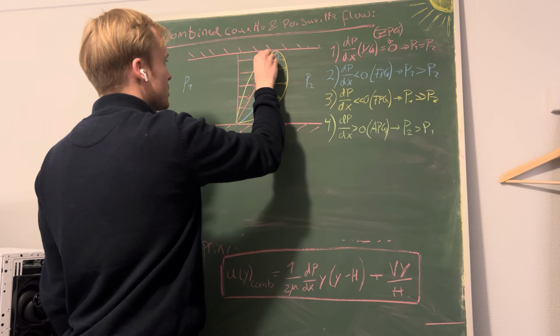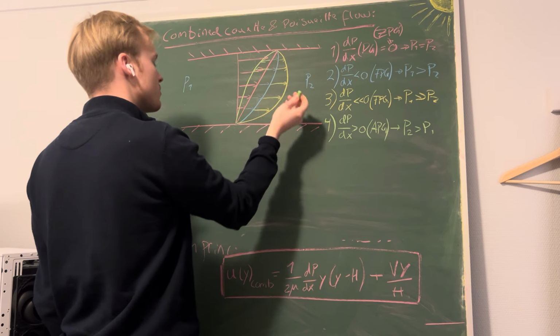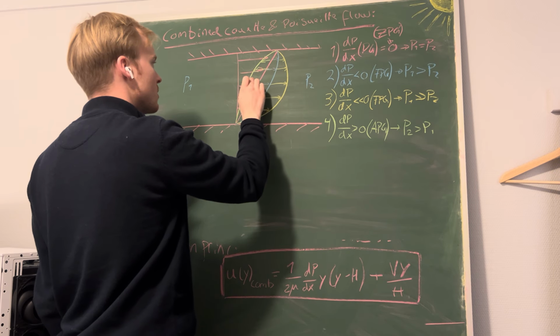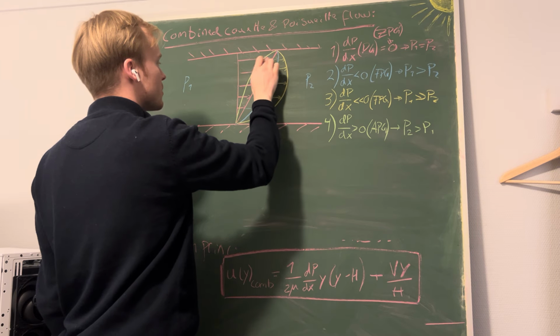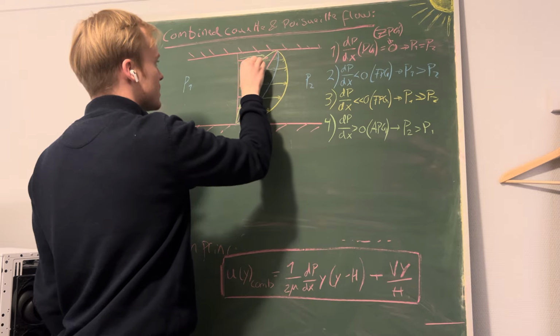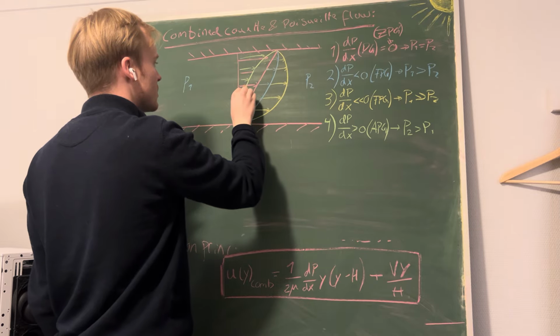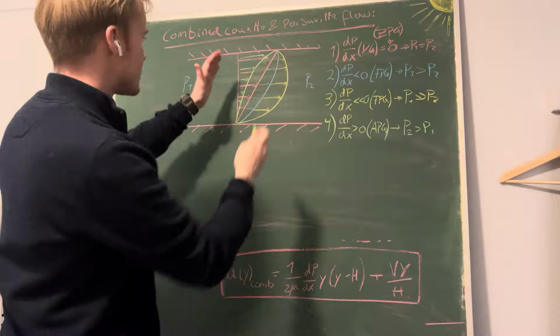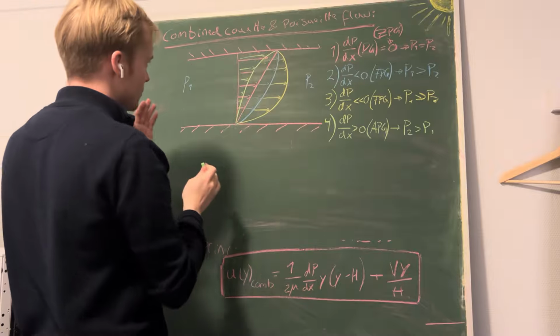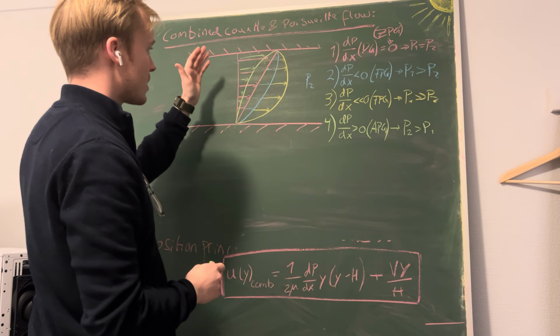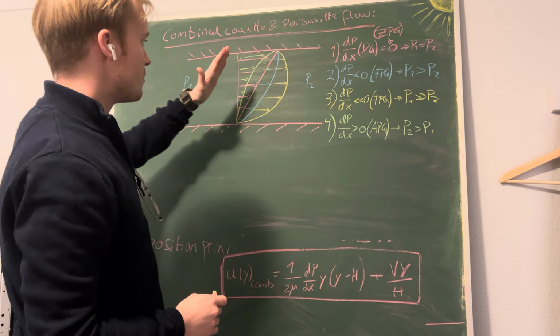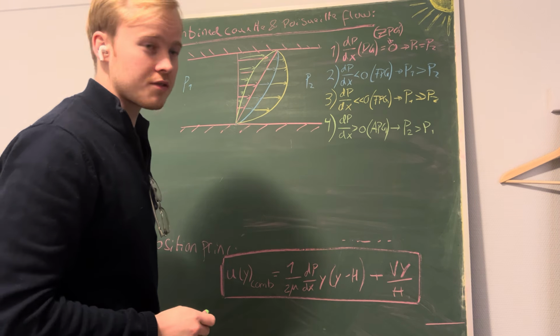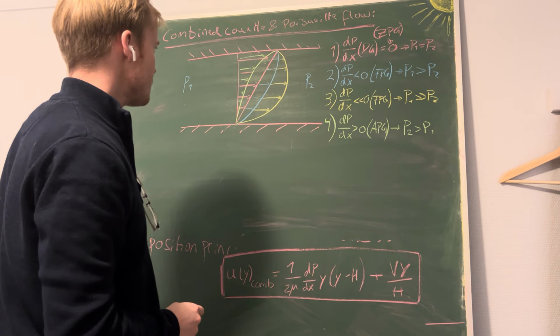So now the velocity profile is tending to the left. Or sorry, these arrows are not correct. It still goes like this. But now we see how it's tilted inwards with the adverse pressure gradient instead of being bent to the right with the favorable pressure gradient.